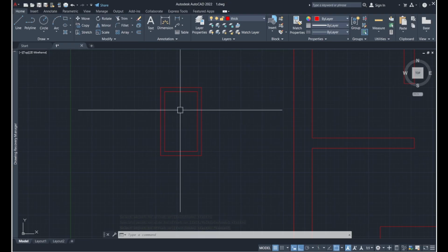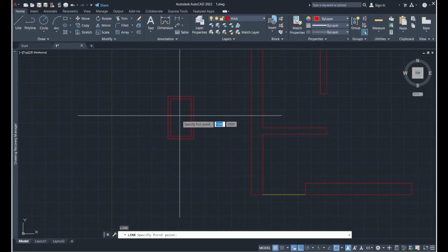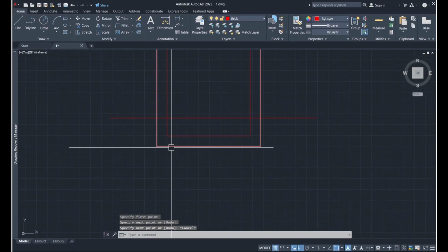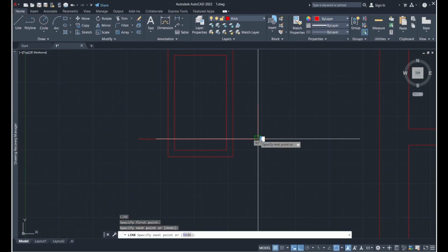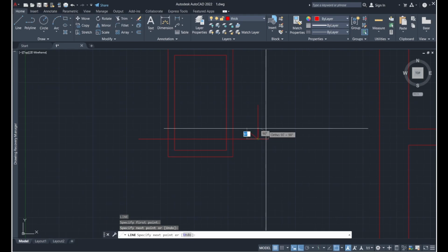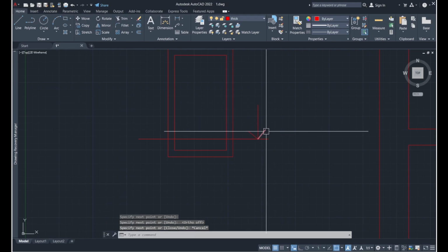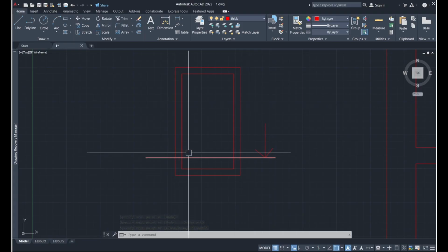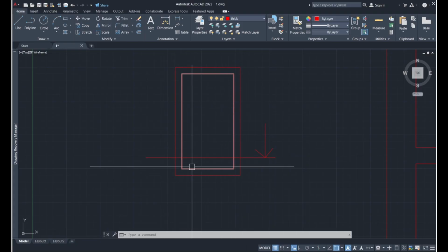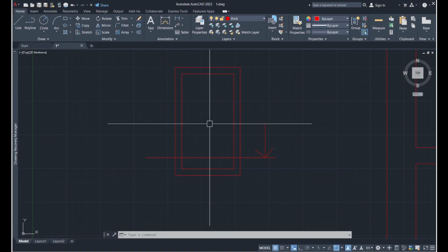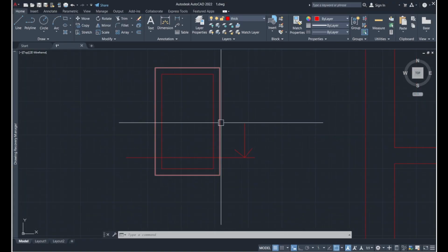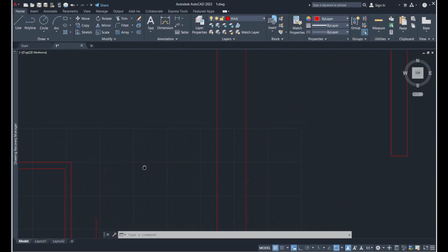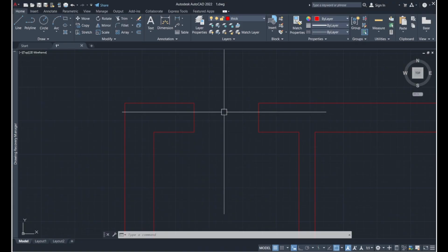Now when I cut my section line, it's going to be represented in this way, and we are going to be looking at it from the top. Like that. So when we cut through this window, we are going to see the thickness of these frames and you're going to see the glass pane itself. So let's try and represent that. So this frame, I've used a thickness of 60. So let's draw the frame first.